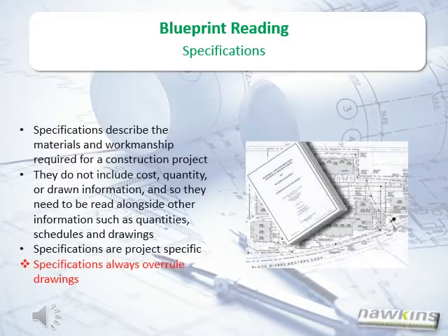Specifications. Specifications describe the materials and workmanship required for a construction project. They do not include cost, quantity, or drawn information, so they must be read alongside other information such as quantities, schedules, and drawings. Specifications are project specific. Specifications always overrule drawings.